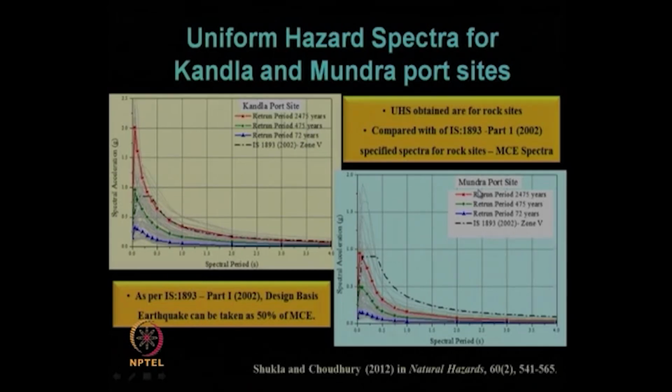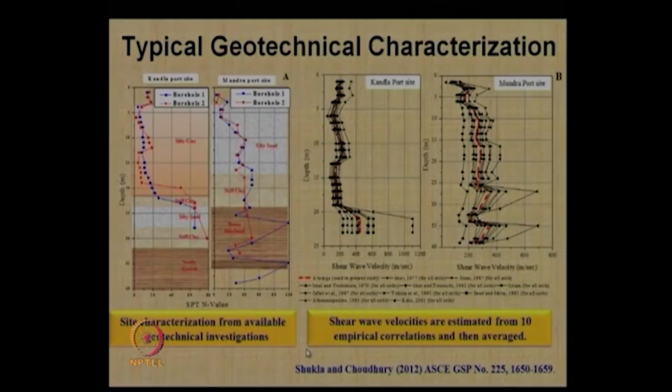Similarly, you can use that for the Mundra port site. This is the spectral acceleration versus spectral period, and as we have already mentioned, MCE has been used for rock site, and DBE, design basis earthquake, is 50% of that MCE.